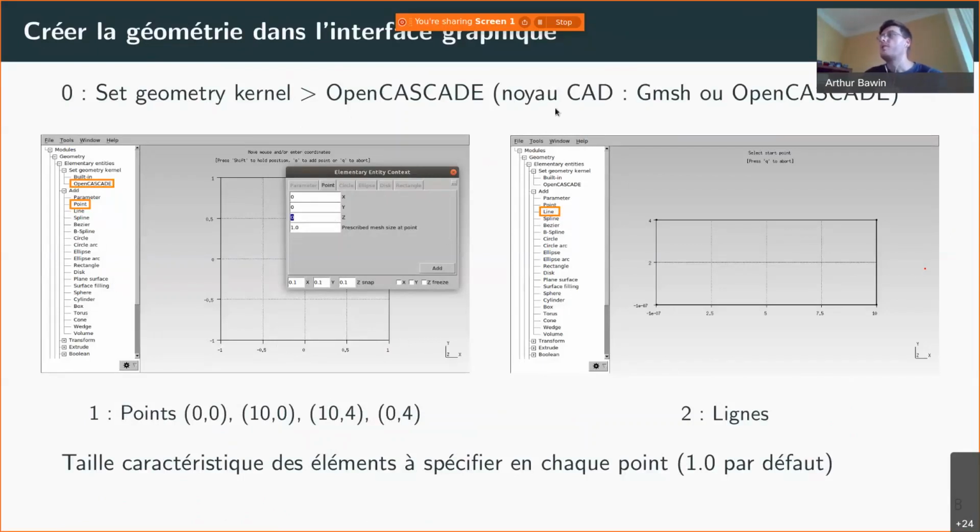There is the built-in native CAD kernel, which makes basic geometries, and then there's Open Cascade, which is used for more fancy geometries, such as ellipses, circles, etc. In our case, since we're going to use a circle, which is an Open Cascade function, we're going to set the Open Cascade CAD kernel. To know which is which, it's all said in the documentation.